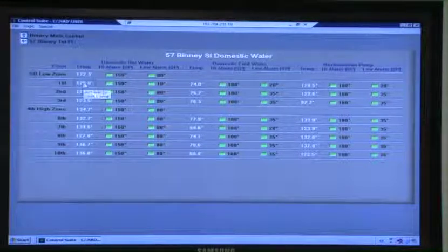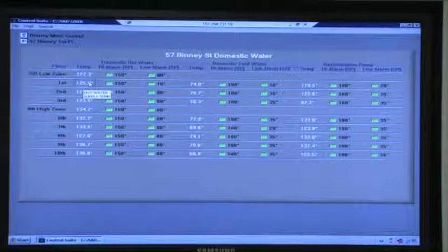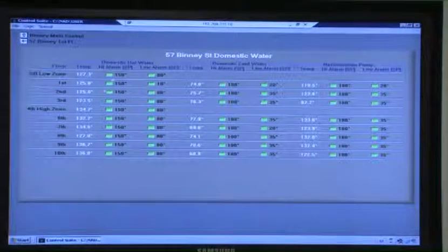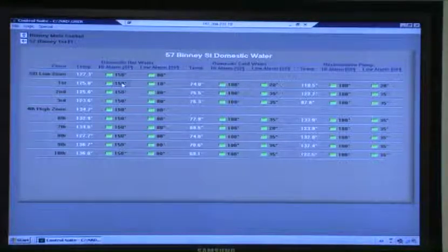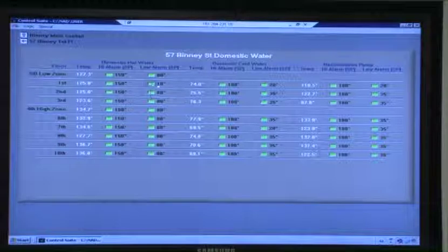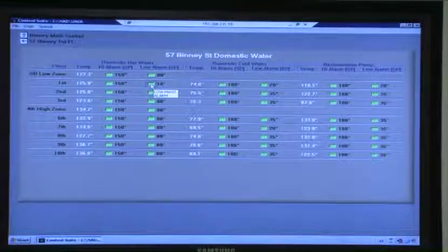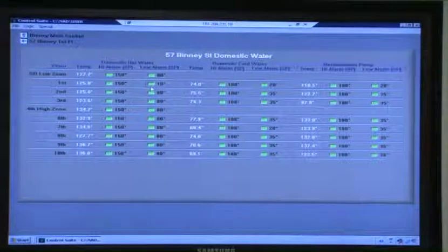It'll tell you the temperature of the domestic hot water coming off the floor. We can adjust them. Timmy can tell us what he wants them at. If the temperature's too high, something's overrunning, we'll know that. If it's low, Timmy's got to tell us, and we'll make adjustments. He wants to know if the temperature falls below 110 degrees supply water.